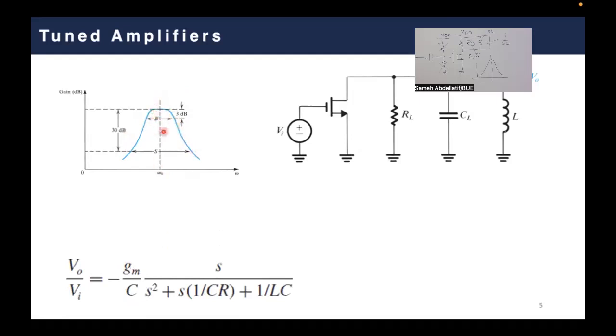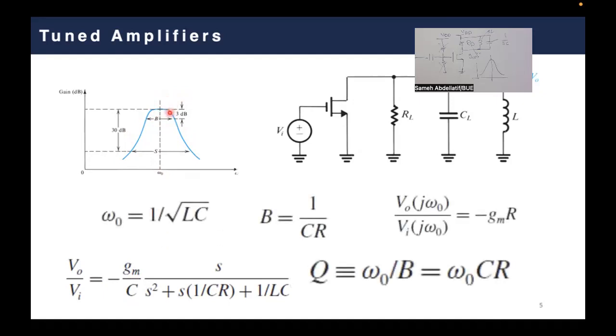This is the circuit, and this is the frequency response as I just described. When you have a resonance here, the point of resonance is simply the point at which the impact of the inductance is cancelled by the impact of the capacitance, making your circuit a purely resistive circuit. And here there are three main parameters we can demonstrate. First is the resonance frequency, which is very straightforward.